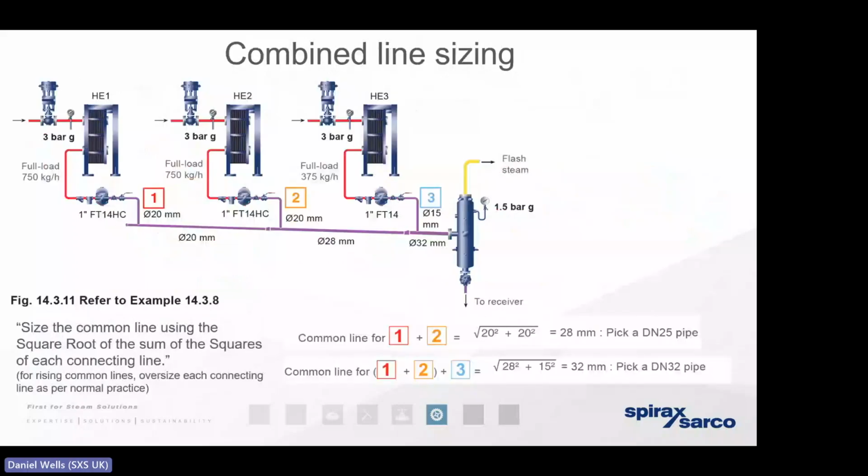Now, that's not to say that the infrastructure downstream of the steam trap can't converge into one common infrastructure. Of course, it can. But it's vitally important that we give thought to the correct condensate loads, not just the mass flow, but also the volumetric flow that is dictated by the single phase liquid, but also by the resulting flash steam that's dictated by the pressure drop. The formula on the bottom of the screen, well, simply put, you can refer to calculators and configurators online that will allow you to determine how we size the infrastructure appropriately.